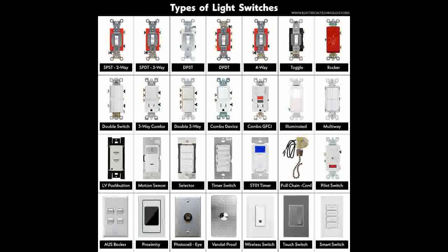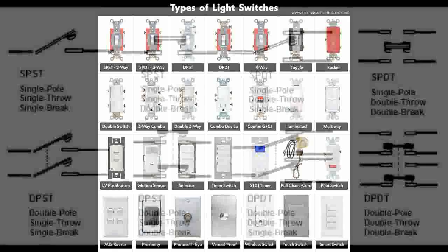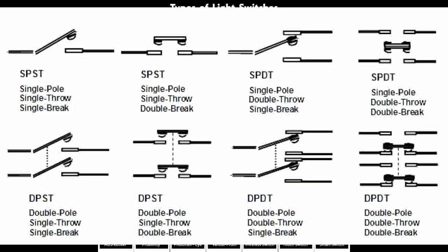The simplest type of switch is the single pole single throw switch, which is abbreviated as SPST. The term single pole means that the switch provides one path for the electron flow and that it can be turned off and on. The term single throw means that the switch controls only one circuit. Single pole double throw switch, SPDT, has one common connection point and can complete a circuit path to two different circuits. However, only one circuit can be completed at a time. There are many possibilities and combinations for a switch of this type.